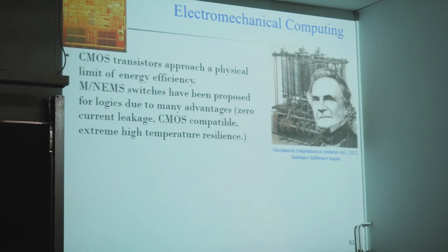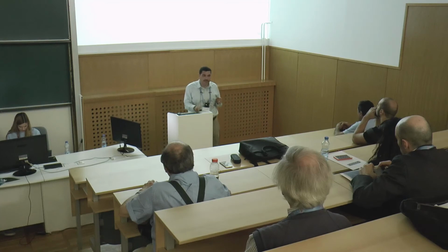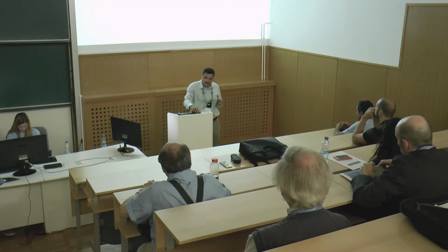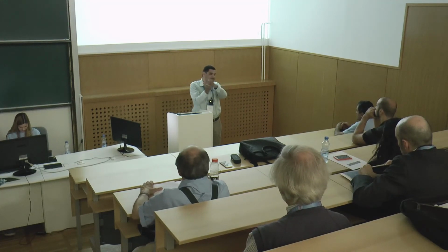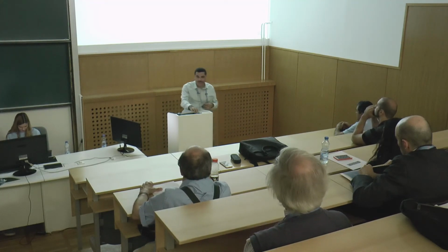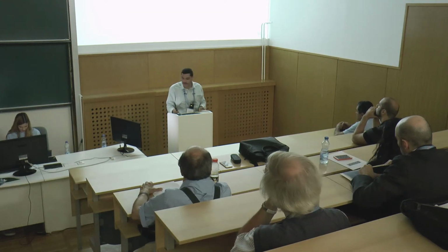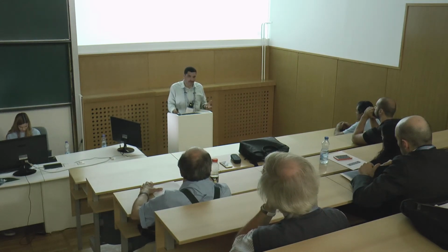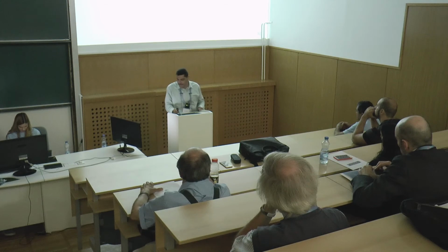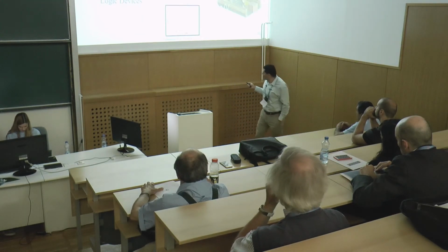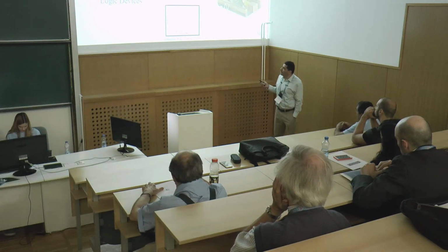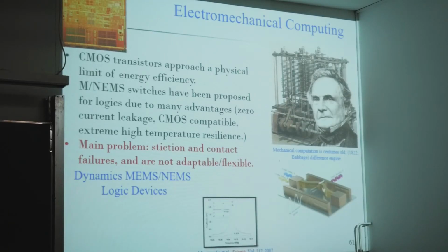The problem with this research based on MEMS switches is that they rely on contact. And the previous presenter said a lot about contact. Contacts present lots of nonlinear effects and issues. So can we do electromechanical logic without contact? Actually, yes, and this is one of the first works, in 2007, which proposed to use logic devices based on the state of the resonator, whether it has high amplitude or low amplitude.